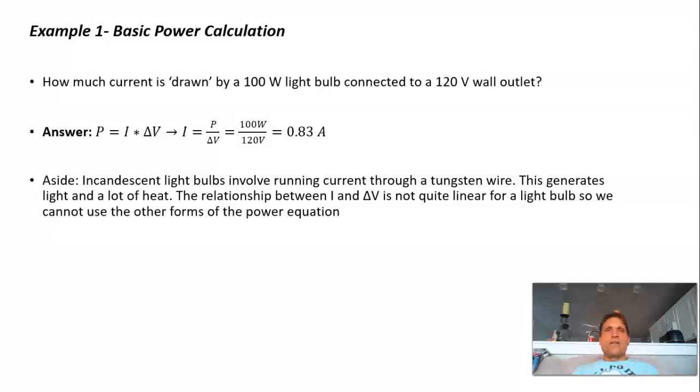Okay, and these calculations are important because in your home, we'll get into this a little bit later, you have several of your circuits connected in parallel. So, for example, your kitchen and your living room wiring might be in parallel. Or the kitchen and the hall. And all of these are in parallel. And if the sum of the currents of everything plugged into those circuits adds up to be greater than about 15 to 20 amps, it'll trip your breaker and your breaker will go off.